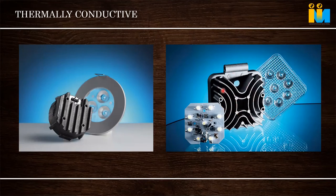Area has to be increased. You can see multiple pins have been given to make more area, because the more the area, the more the heat transfer happens, because air goes there and the conduction, convection and heat transfer happen that way. Convection, radiation. So area has to be increased. That's how the design has been done.